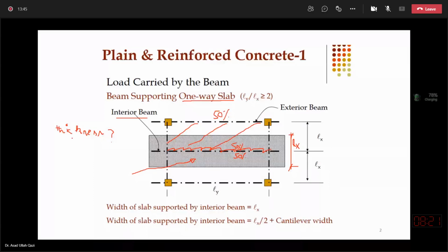Here, since we are at the moment discussing beams, if we know that this slab has the thickness 150 millimeter, which is the h of the slab, and furthermore, above this slab there is a floor finish. We have the architecture working drawings, and from the section we got the idea that the floor finish proposed by the architect is of thickness 100 millimeter, which might be a composite of brick ballast and terrazzo or some PCC and tiles.